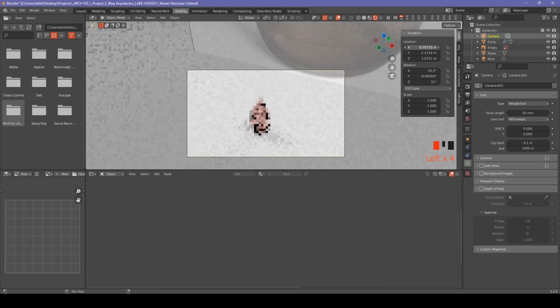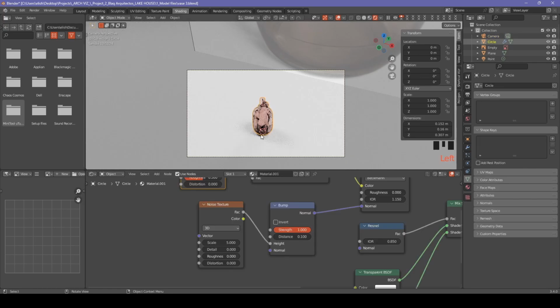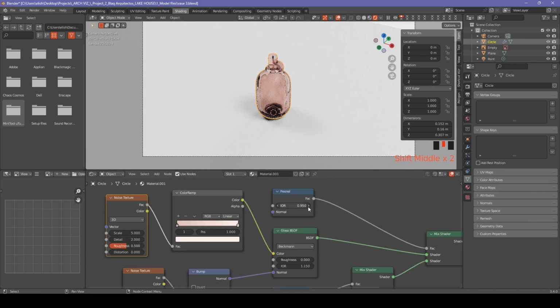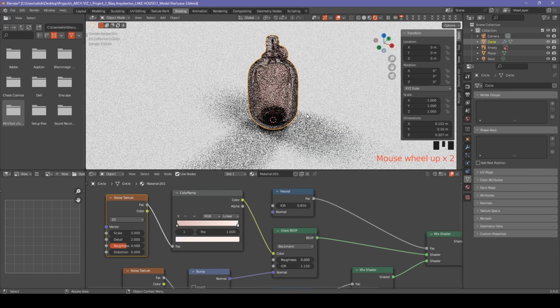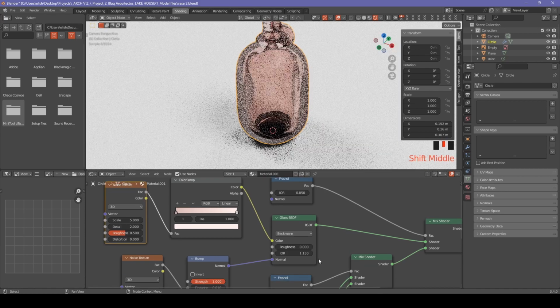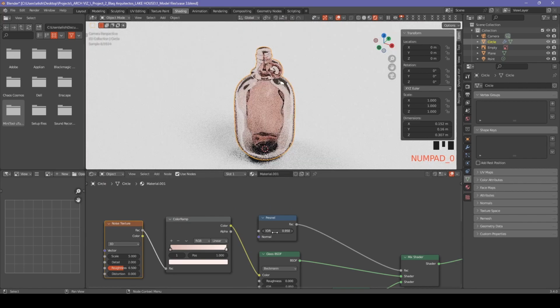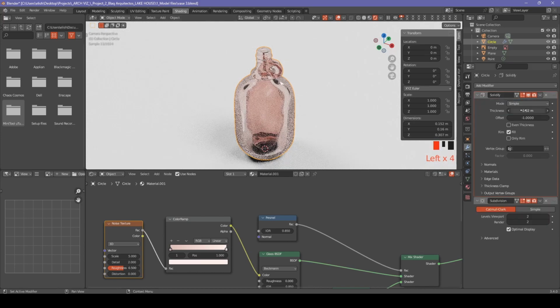As we can see, our material texture has screwed up a little bit, and we are going to fix it now. So we are reducing the bump distance as well as adjusting the Fresnel values to make sure the glass thickness is not like 5 centimeters or so. Also, make sure you adjust the solidify modifier to make sure the thickness of the glass is not too large.